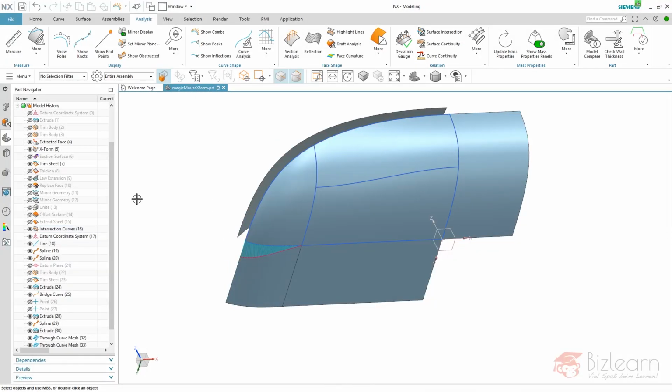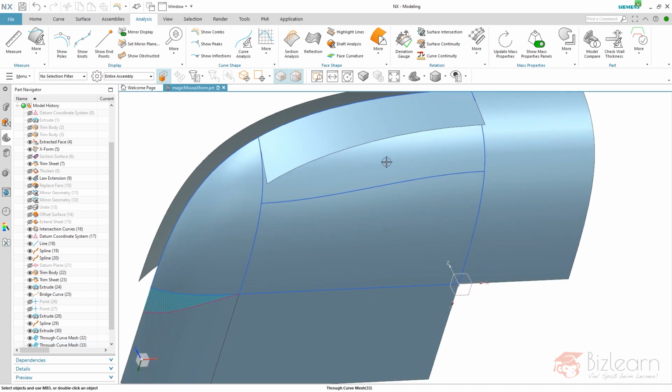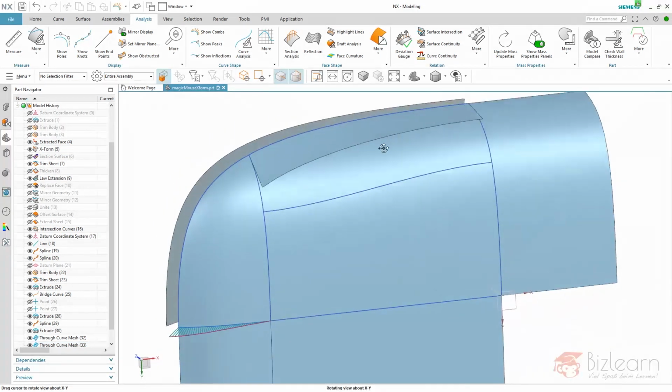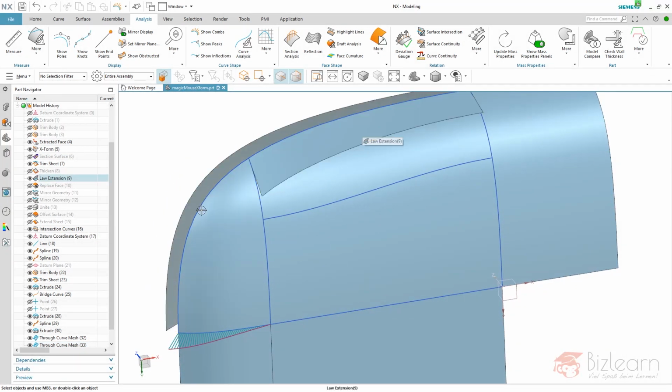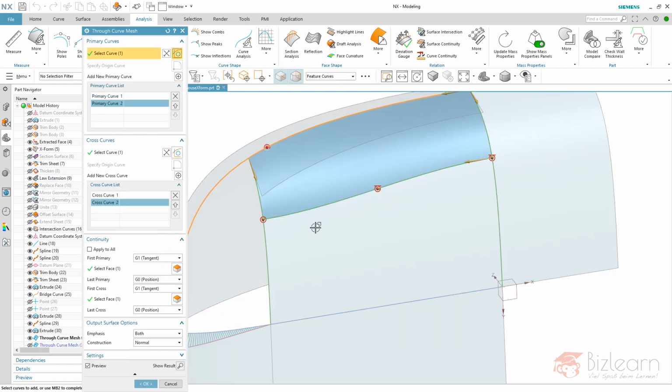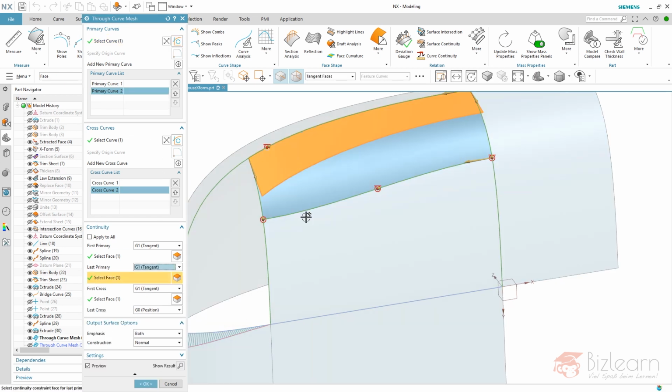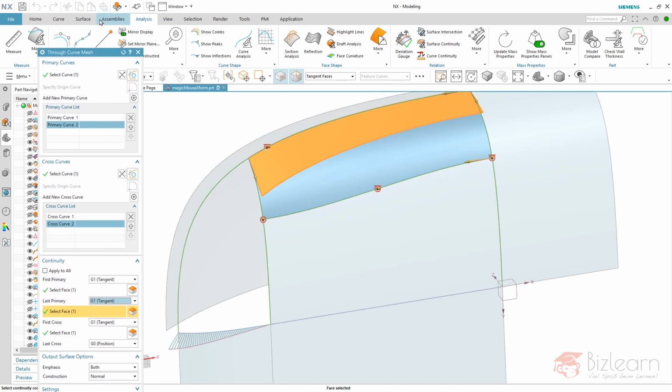I told you before I started doing these surfaces, there is a possibility of using this one as an input. And you can try that, of course. So this is my second primary here. So I can create a relation which is tangent to this one. And you can see there's no alert, but I also will check the knots. We don't have knots, poles are fine.